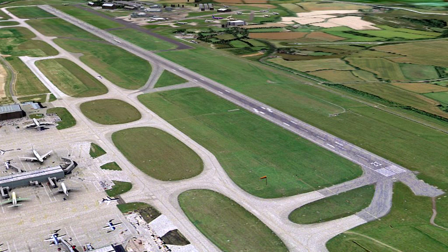Because there is very little friction between the wheel and the runway surface, the wheel cannot be retarded efficiently by the brakes. Otherwise the wheel will lock, and the wheel friction with the runway will reduce even further. This is most obvious when ice is present on the runway.